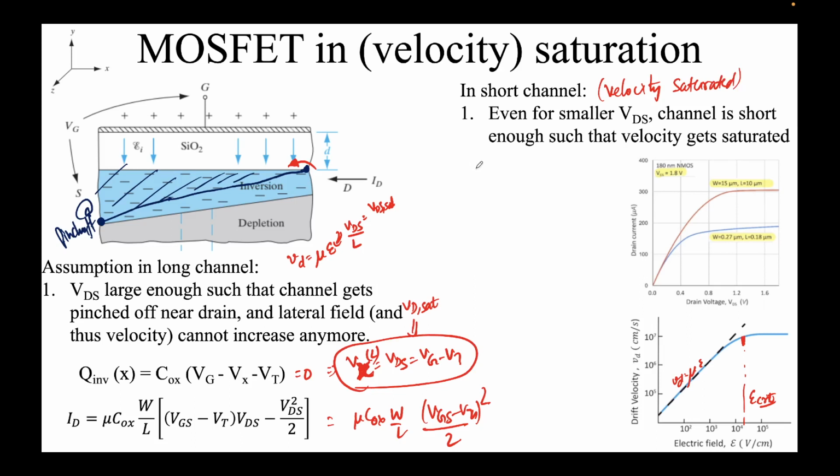Let's try to find out the electric field in a long channel first. Say you are applying 1.6 volts, so VDS divided by L. So 1.6 volts divided by L. What is the L that is given for this long channel? This is given as 10 microns, 10 micrometers. Units are centimeter here, so this term will be 1.6.